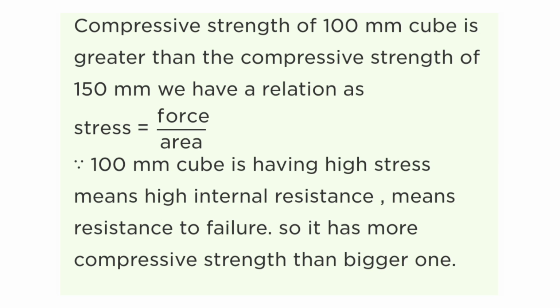Stress is equal to force by area. The 100 mm cube is having high stress, meaning high internal resistance, meaning resistance to failure. So it has more compressive strength than the bigger one.